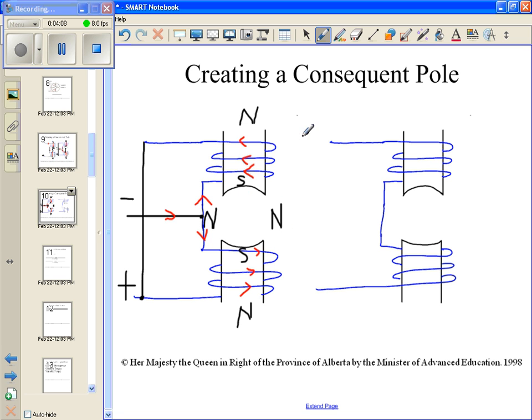If you recall from understanding your rotational frequencies, mechanical versus electrical, if I add a set of poles, that is going to cut my speed directly in half. Again, the speed we're cutting in half here is the synchronous speed. Do not confuse that with the full load speed. Let's take a look at the one on the right.